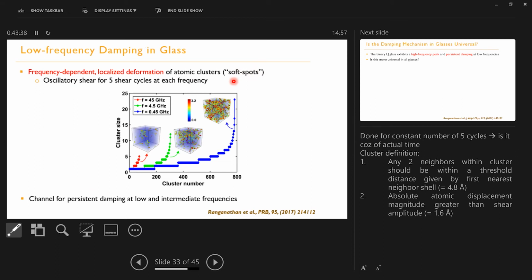The interesting thing here is, if you consider a perfect crystalline structure, all the atoms are occupying the lattice position, and these atoms cannot occupy any other position. They can diffuse to other lattice points, let's say, but they typically cannot occupy interstitials or voids in the structure. Whereas the glass structure doesn't have long range order. It has short range order, but no long range order. There is no periodic arrangement.